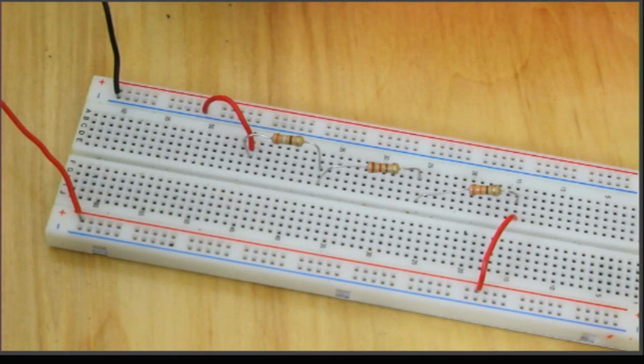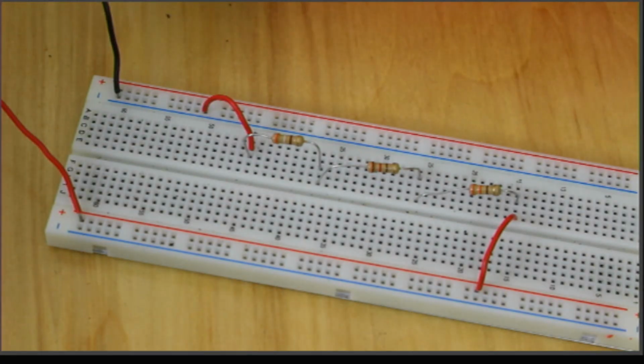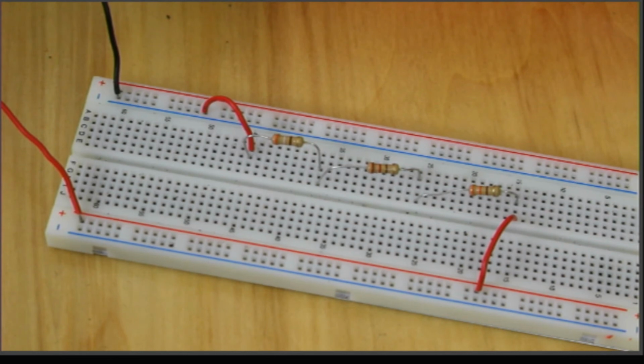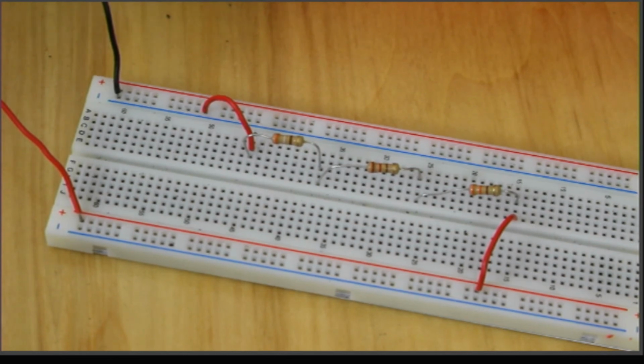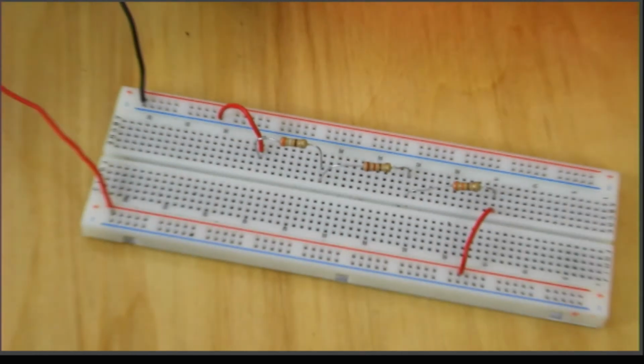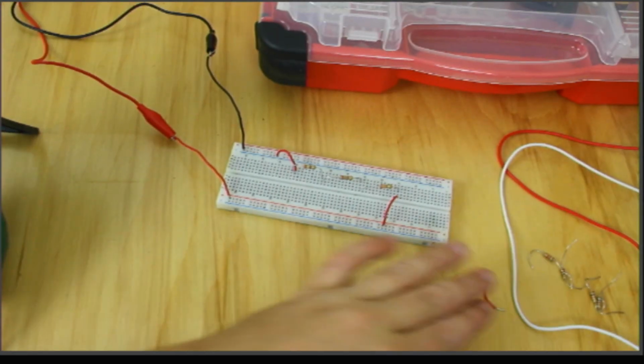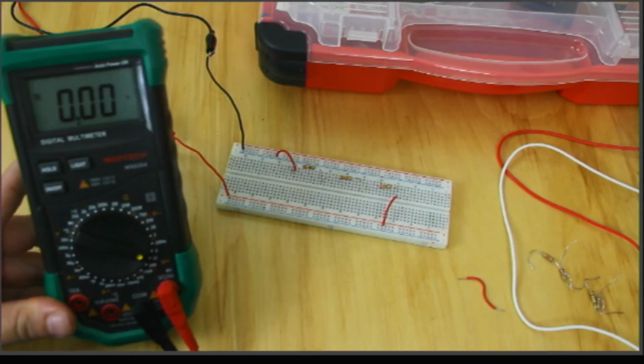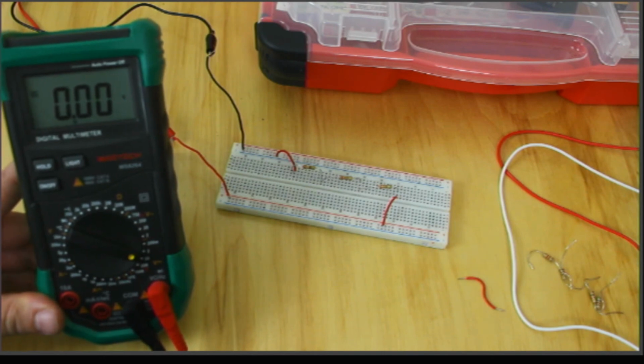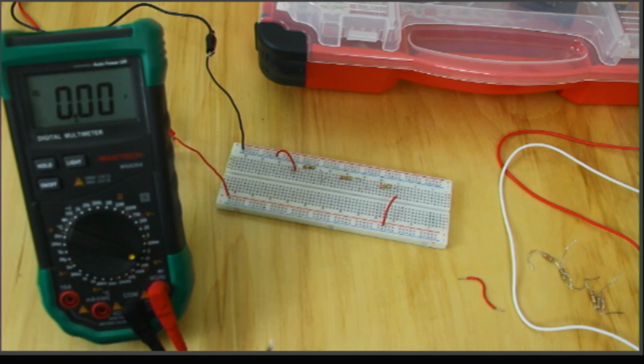Okay, now right now the circuit is live and running because I didn't put a switch on it and I didn't leave anything unconnected. So right now it should be working. So let's find out. All of my voltages are above 2 volts, so I'm going to stay in the 20 volt DC range on my DMM. So what I'm going to do now is I'm going to pull back just a bit. I'm going to put my DMM in frame, make sure there's no glare, and I'm just going to start measuring these.